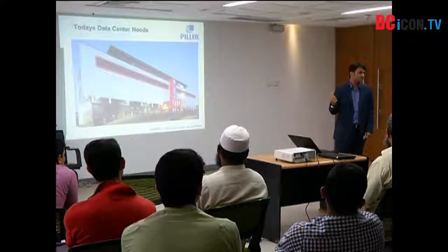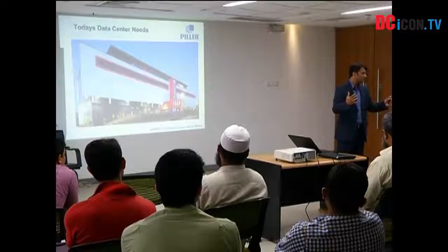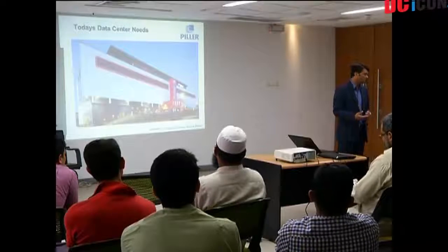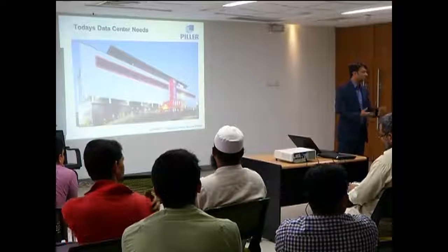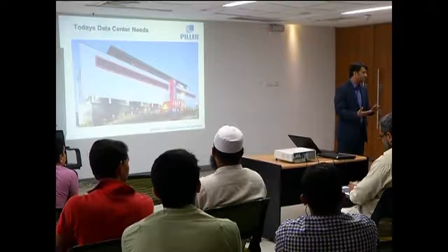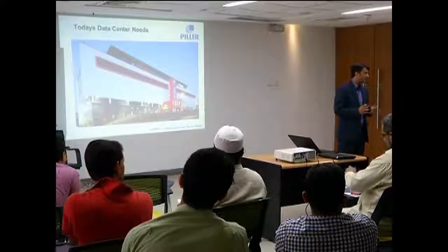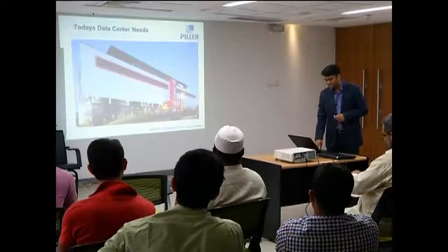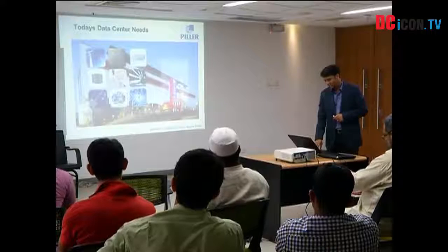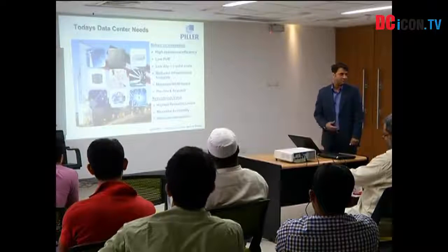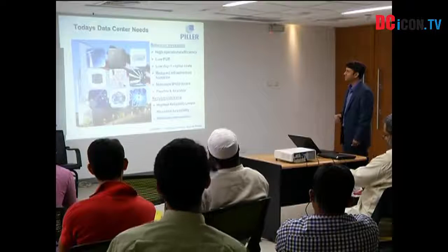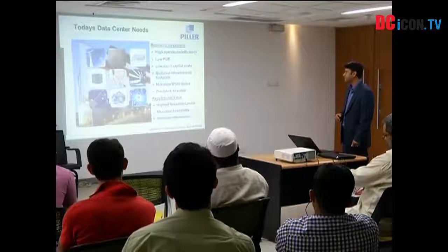Yeah, that's what I mentioned. So the output is generated using a motor generator or a synchronous generator, and that is why it is called rotary, because we are generating it with a synchronous generator, not with any MOSFETs or IGBTs. So that is why it is rotary. So coming to data center needs, we know these terms from mostly all the products. We will try to fit in how Pillar fits into today's data center needs.